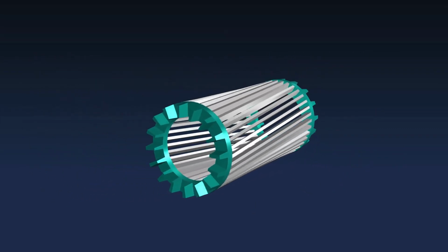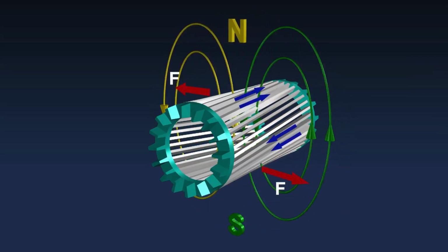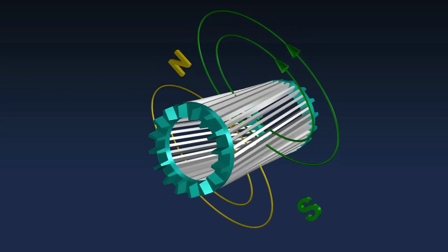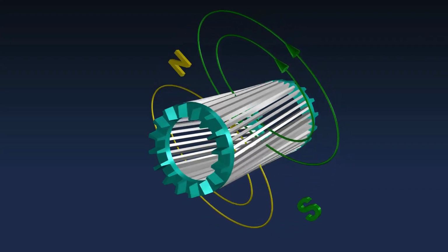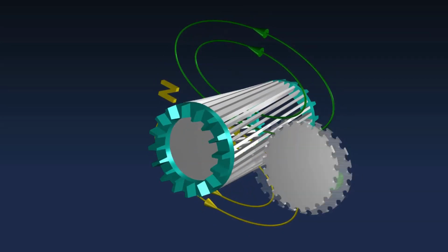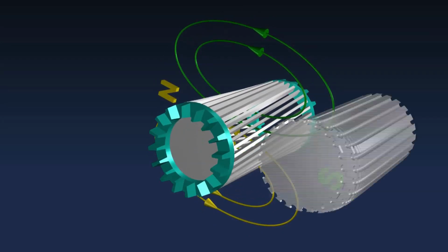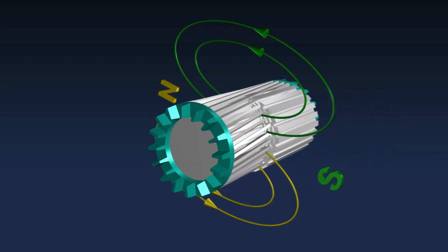The rotor, similar to a squirrel cage, is placed inside the magnetic field. Current is induced in the bars of the squirrel cage, which is shorted by the end ring. As a result, the rotor starts rotating. To aid such electromagnetic induction, insulated iron core laminations are packed inside the rotor. Such small slices of iron ensure that the eddy current losses are minimal.